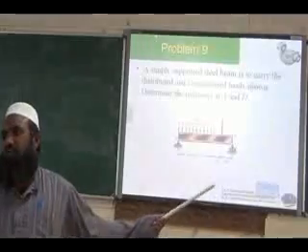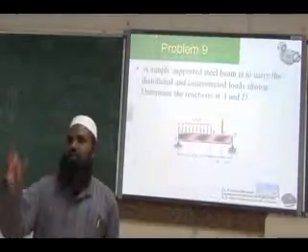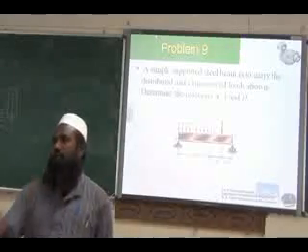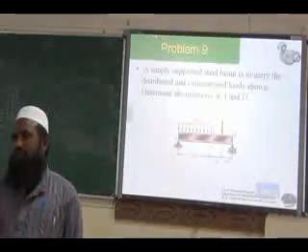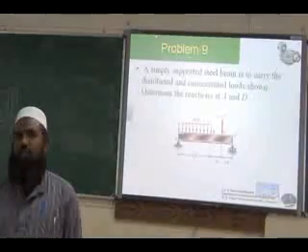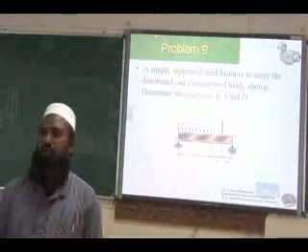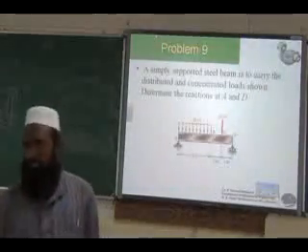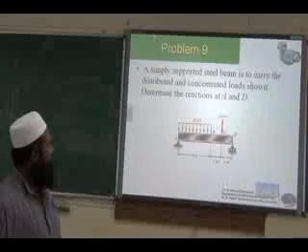So you will have two vertical reactions. It is not allowed to move in y direction only. So AY and BY you will have. After considering all the forces, now find out the unknowns. You have to find the unknowns either by using the sigma F equation or the sigma M equation, or both. That is the procedure.